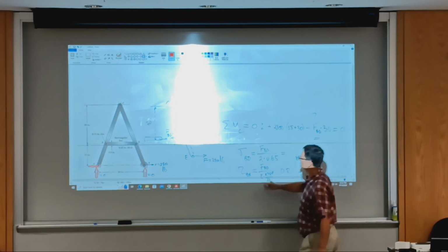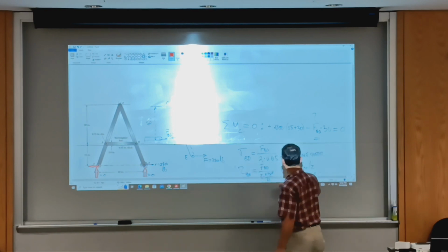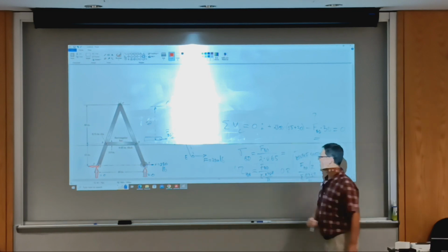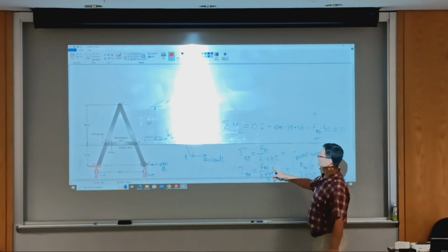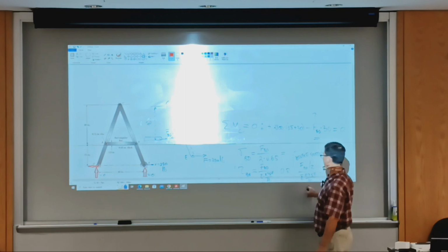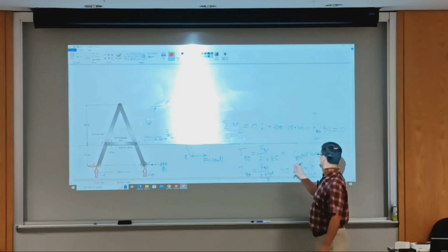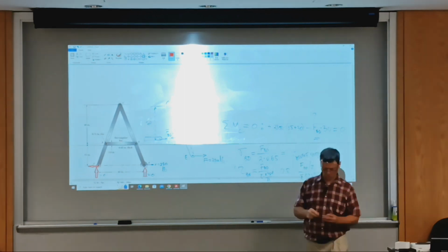This is single shear. Check the text of the problem. It may say if it's single shear or double shear. You can think of it two ways: either they share the load, or you double the area because it happens in two places. Sharing the load might be more intuitive.